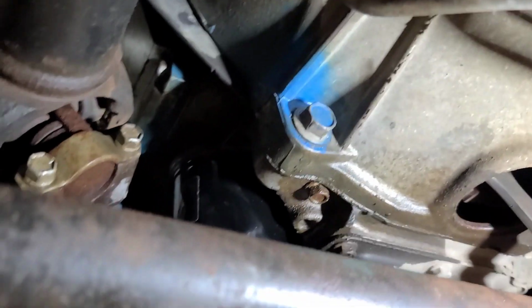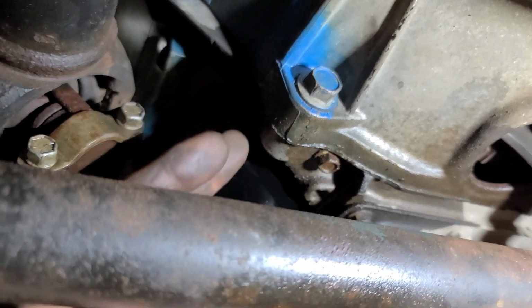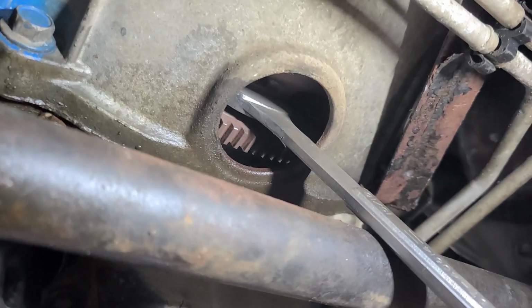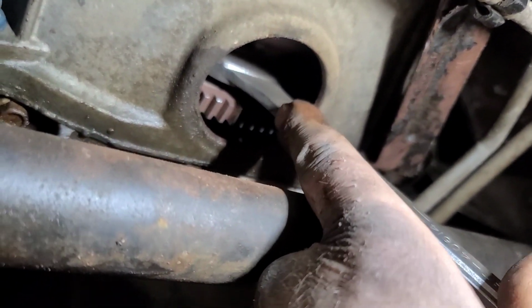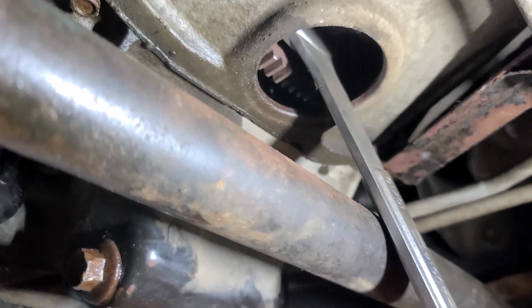So the factory has a holding fixture that goes in where this plastic cover is, but it's nearly impossible to get in there. So I've modified a 15/16 open-end wrench, and I put it on the lug of the torque converter, which is obviously bolted to the flywheel, and that goes up against this hole. Now I had to modify the wrench slightly. I had to make it a little bit thinner to get it in there, but that will hold.